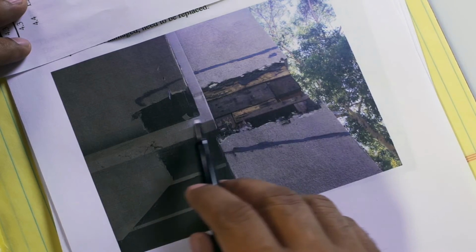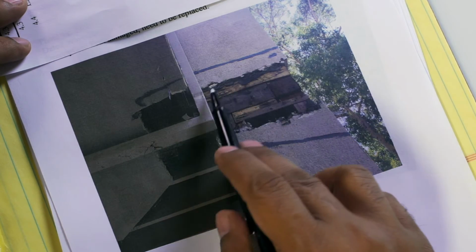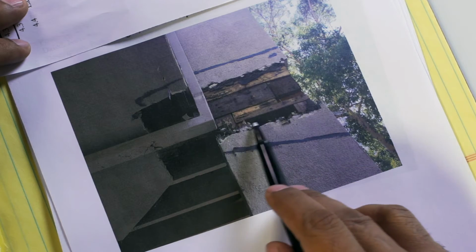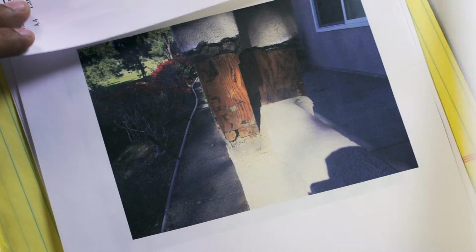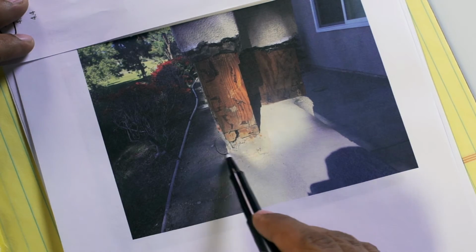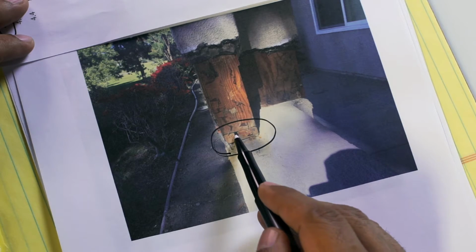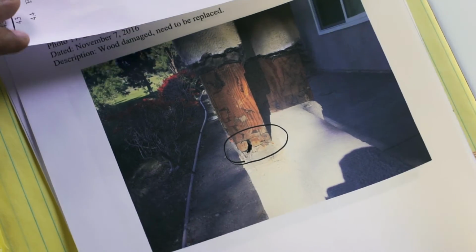And I want to show you an example of a couple of inspections that we've done recently of exactly what happens. And I'm going to try to hide the name of the property, but here's an example. This is on some balcony decks. And what we've done is we've taken the stucco away and opened up these decks in order to look at the condition of the wood. And you can see right in here, you can see the termite infestation where the wood has been completely eaten. You can see over here, the base of the post is completely eaten. You can see the holes in the wood.